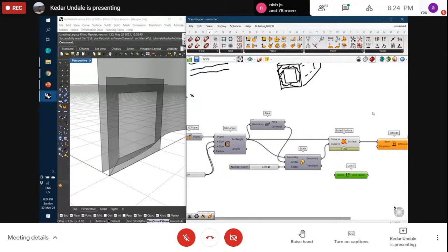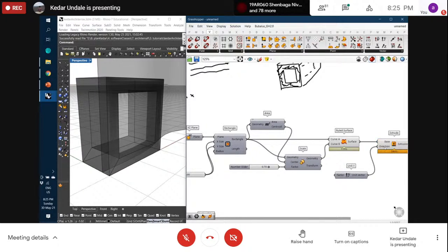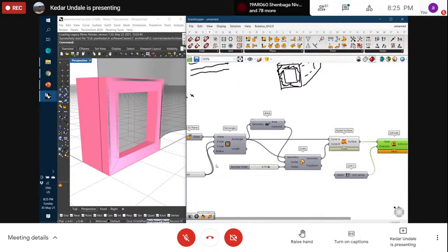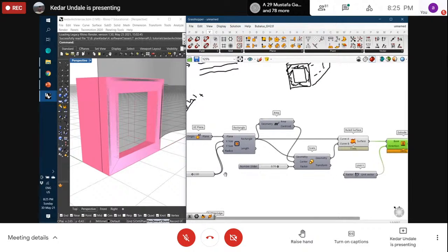So you see, every time that you are doing something inside of Grasshopper, you are telling it what to do. It's not going to automatically do something. It's basically like working in SketchUp, but you're telling it each and every step. You have to extrude in the Y direction, you have to give it this thickness, and so on and so forth. So we give it a thickness in Y, but we know that the size is 2, so we connect the same 2 to the factor.